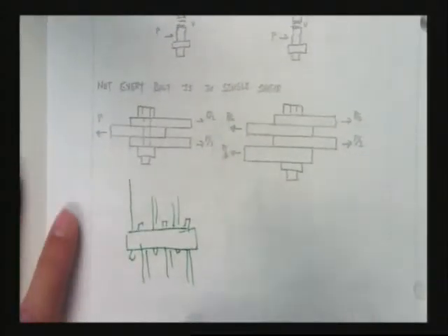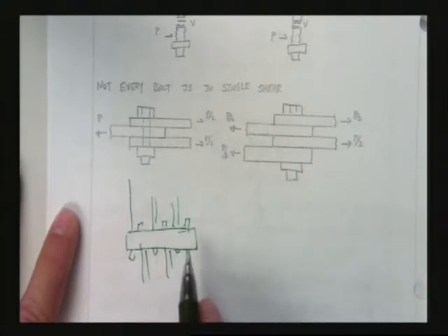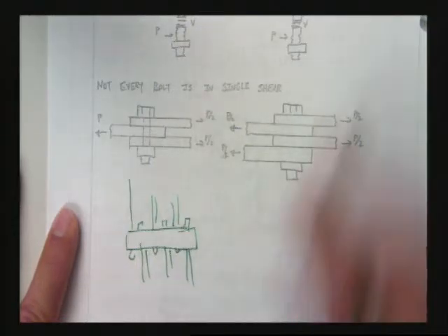So that's what they do. That's what double shear, triple shear, quadruple shear is. This is very common. And if you're ever in Pittsburgh, there's a famous, I think it's called a lenticular truss, and it uses these type of connections. Okay, and that's why they did it. It's just to make their pins smaller. Okay, save money on pins.